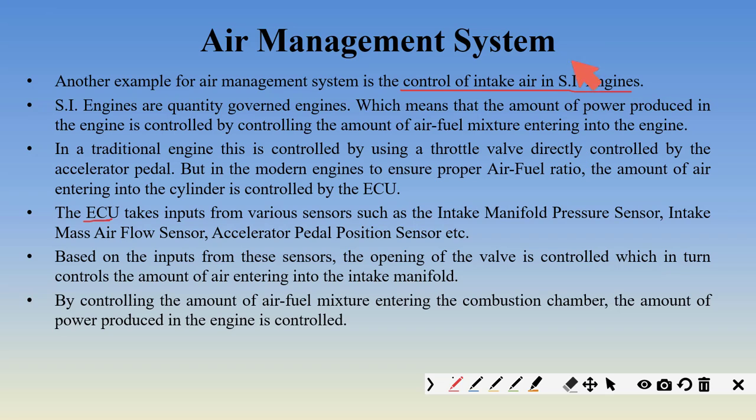What will an ECU do? ECU will take in inputs from various sensors such as what? Manifold air pressure sensor, intake air temperature sensor, engine speed sensor, throttle position sensor, and many others. Based on inputs from all these sensors, the ECU will send a signal to a stepper motor.